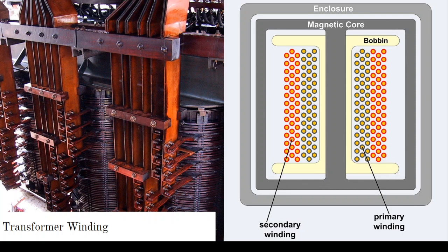The most important thing in windings of transformers is to understand how it's assembled. You talked about wood-based laminates. So you have wood-based laminates to hold these multiple terminals for your primary and secondary. So you have multiple sets of windings. You have different stacks. In other words, when you have the windings manufactured, they are manufactured as stacks, and they are stacked up together to identify the turns for primary and secondary.